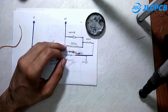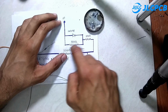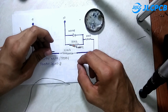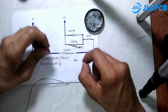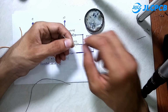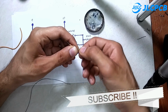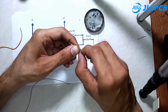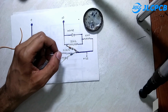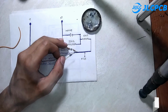Okay, so it's done. We have made this, and now we are only left with this 22 kilo ohm resistor, which I'm going to connect here after the 10 kilo ohm resistor. Here we go. Solder it again. So it's now soldered.